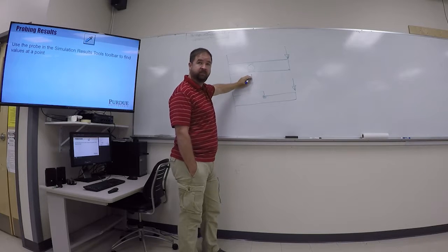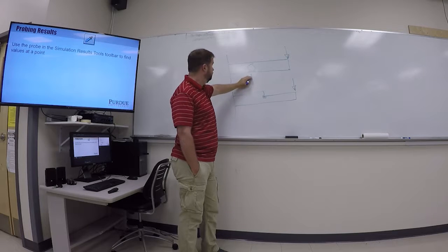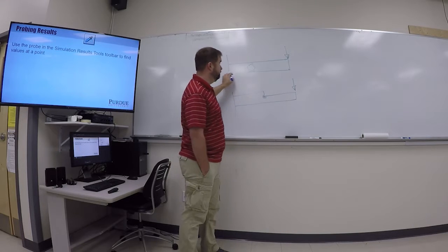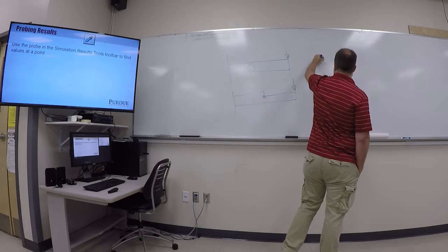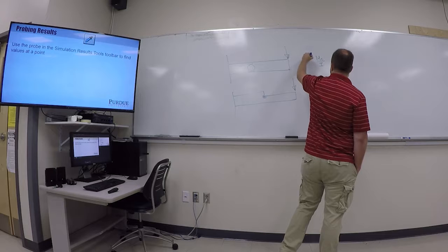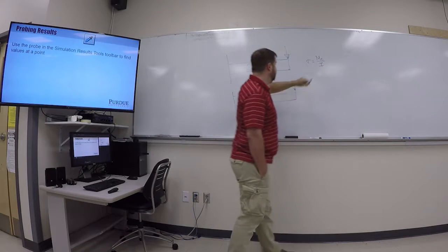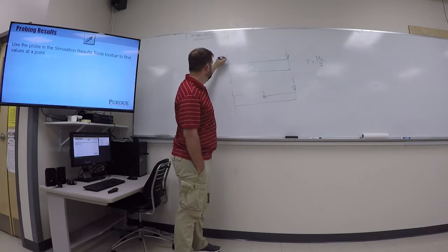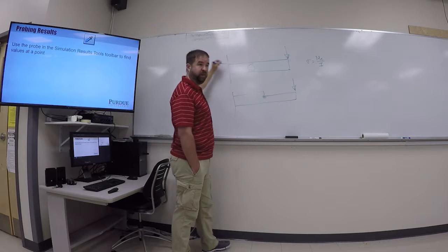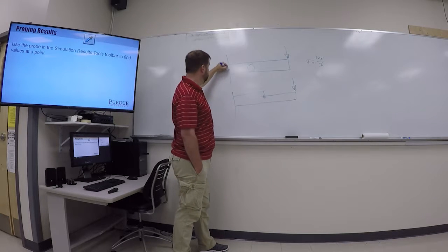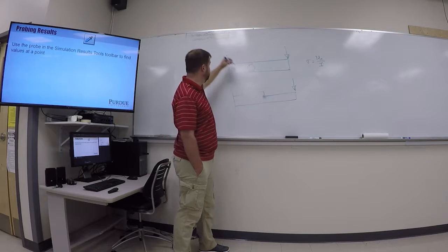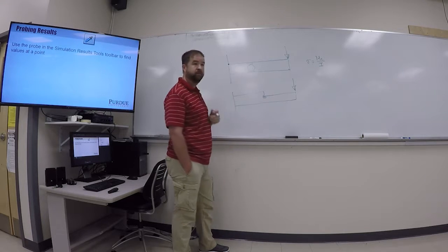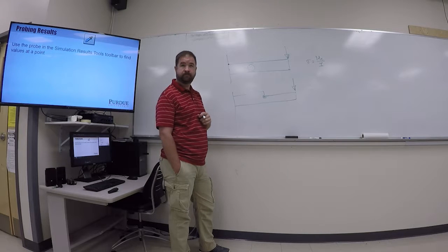If I want to check my stress values to my hand calculations, if I do just a simple calculation, stress is equal to MC over I, and I use the whole length of this beam and the moment that is over here at the edge, my MC over I equation is going to tell me the stress that should be up here, right? Okay?